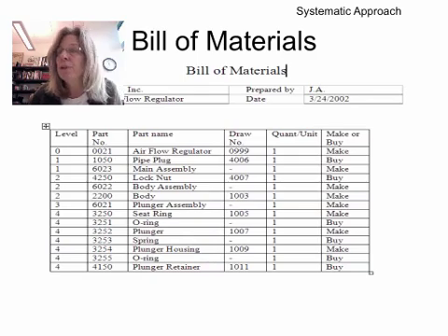Something that looks very similar to a parts list is a bill of materials. I know you've seen a BOM, and you've seen both the parts list and a BOM, but understanding the differences in the two is going to be important for you. There are two main differences. One is that we have this column that indicates the level. Those of you who have had IME 410 understand that this level is associated with MRP.